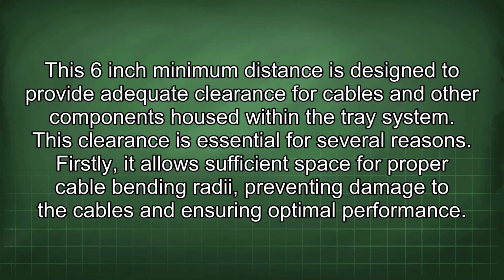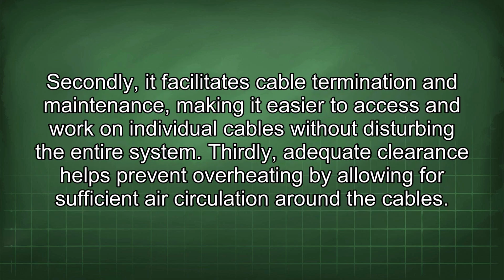Firstly, it allows sufficient space for proper cable bending radii, preventing damage to the cables and ensuring optimal performance. Secondly, it facilitates cable termination and maintenance, making it easier to access and work on individual cables without disturbing the entire system. Thirdly, adequate clearance helps prevent overheating by allowing for sufficient air circulation around the cables.